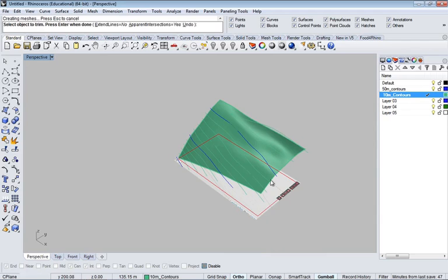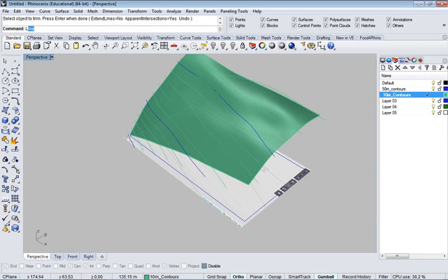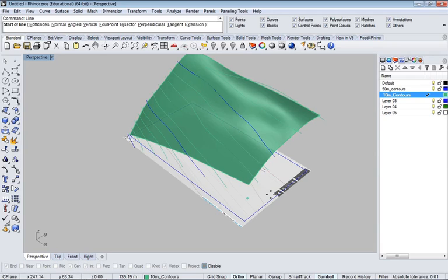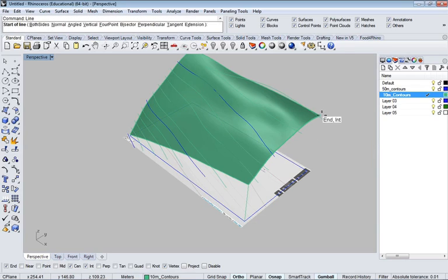So from that surface, I can then go and use the edges and some of these other pieces. If I was going to create a solid model, I might turn on the object snaps, and go and select these endpoints to start drawing some lines from the endpoint.